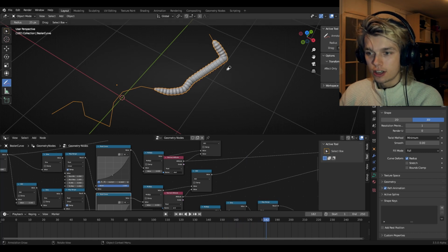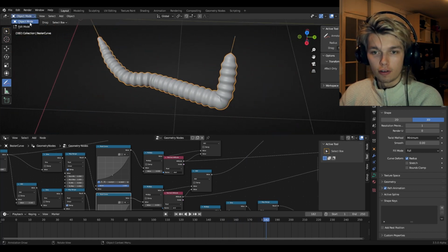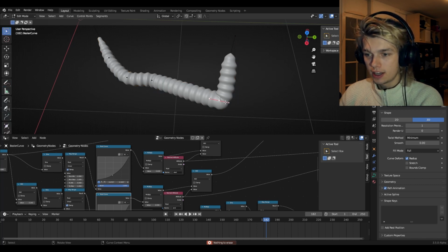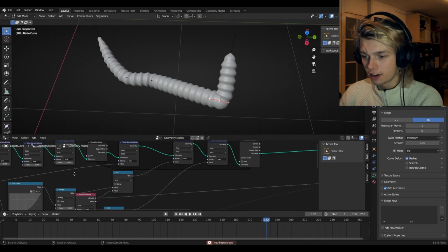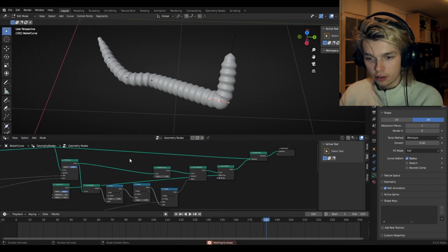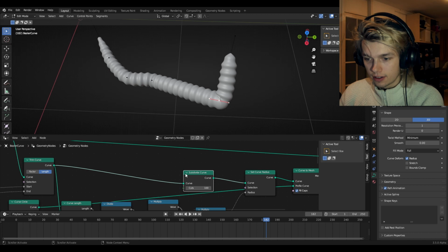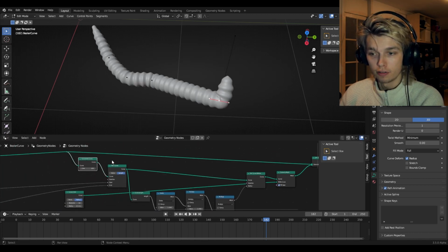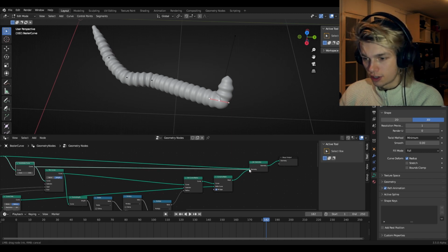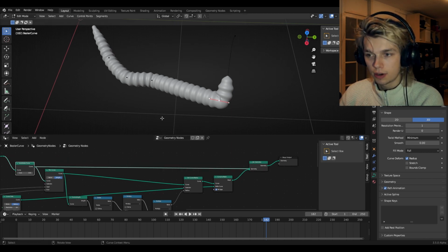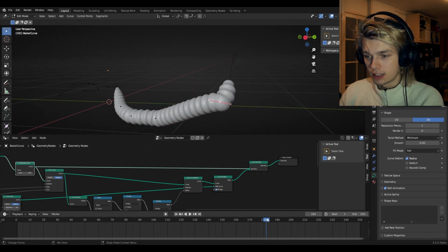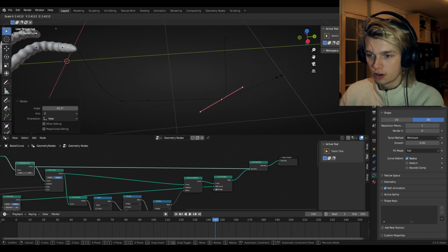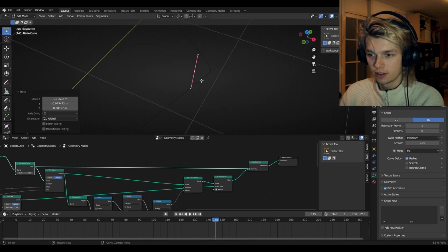All right. So we need to do some troubleshooting. Of course, here the corners are maybe a bit too narrow. So we can probably do that a little better by going to our curve here and just copying this subdivide curve node. Or actually, we can put it before the trim curve and then connect this to our join geometry. Let's just get rid of this part then. And let's go back a little bit. Yeah, so we don't want to have two sharp corners, so we can change that up a little bit.